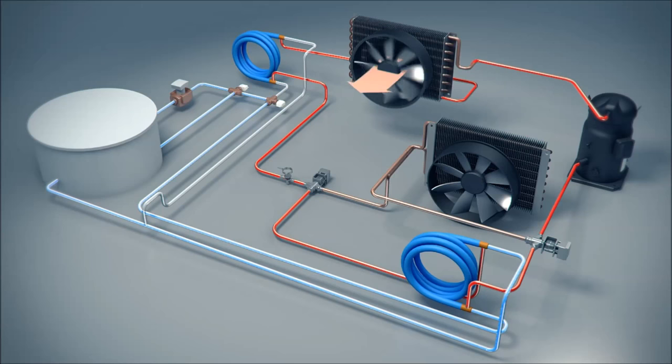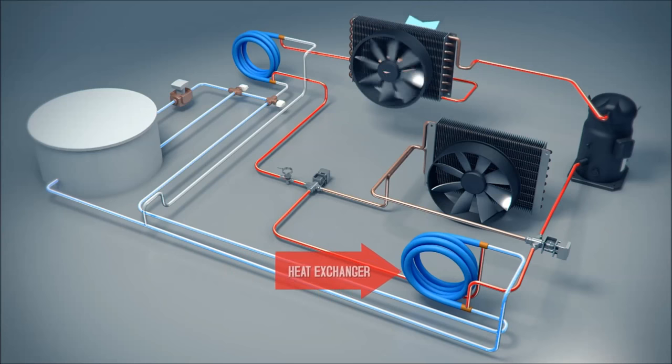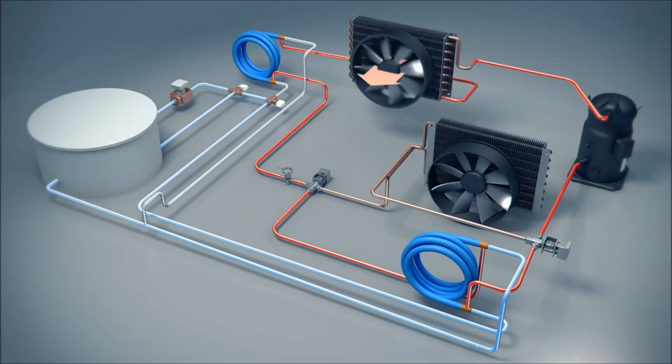This is facilitated by substituting an AC Companion heat exchanger in parallel to the standard air conditioning evaporative coil. The air conditioning evaporative coil is isolated or taken out of service from the refrigerant loop of the AC Companion charging loop by employing two refrigeration isolation valves.